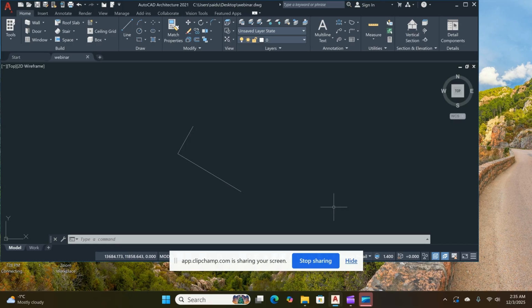Curve segment example: chord bearing north 62 degrees 59 minutes 45 seconds east, chord length 7.17 meters, radius 20.12 meters, and we had arc length 7.21 meters.